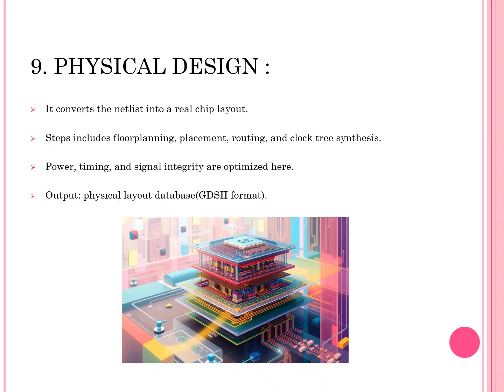And clock tree synthesis, which ensures that the clock signal reaches all parts of the circuit with minimal delay. During this stage, we also optimize for power, timing, and signal integrity to ensure chip performance and reliability. Finally, the output of this stage is the physical layout database, commonly in the GDS format, which is then used for fabrication.